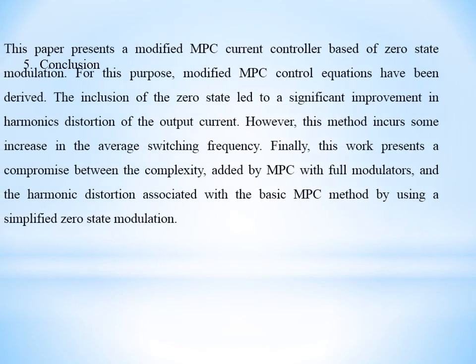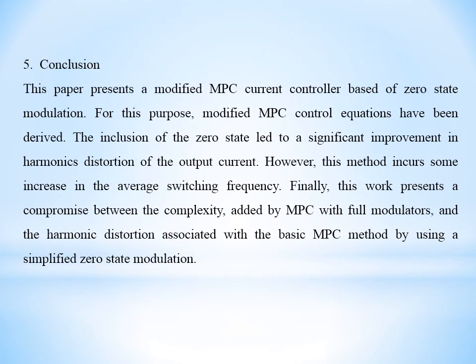Conclusion. This paper presents a modified MPC current controller based on zero-state modulation. For this purpose, modified MPC control equations have been derived. The inclusion of zero state led to significant improvement in harmonic distortion of the output current.